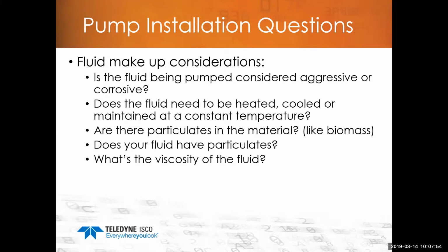Does the fluid need to be heated? Heating and cooling can affect the flow rate of viscous materials especially, and other types of chemicals that are out there. So when you're looking at installing the pump, you want to make sure that if you need to have the material heated to a certain rate, one, go back to what we said earlier about space and location where you're putting the pump, but also, do you need to have a cooling bath or a heated temperature jacket to put the fluid in the state that you need it? That way it moves and flows through the system at an optimal rate, not just into the pump, but through the valves and through the piping, okay?